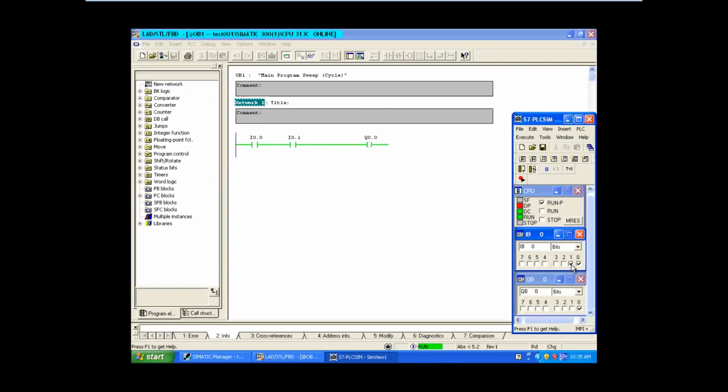So you can conclude that unless or until you disturb the switch, it will not give supply. What is the supply I am meaning here? Supply is coming up to this. Fine. It is not crossing this contact. Why? Since the normally open contact is not pressed, it is not allowing the supply to enter.